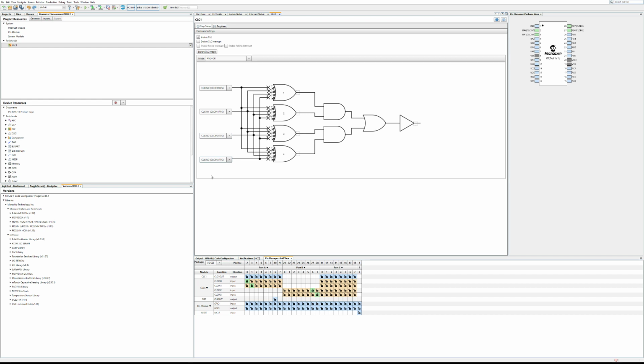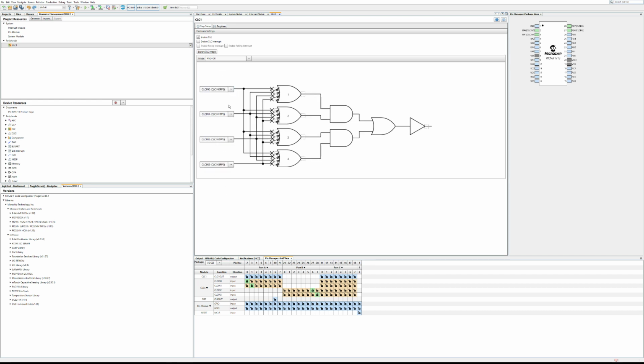Now there are a variety of other inputs you can use here. We've got the outputs of the comparators, the outputs of timers, the outputs of a PWM driver. You can directly drive it from the serial peripheral, timer overflows and matches, the TX from the software serial port, zero crossing detector, etc., etc. It's very liberal in where you can get your inputs from. This list also changes depending on what pin you're looking at, at least in most devices. So there will be some differences in this list depending on whether you're looking at the first, second, third or fourth input.